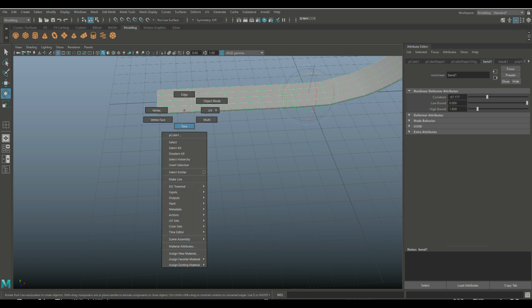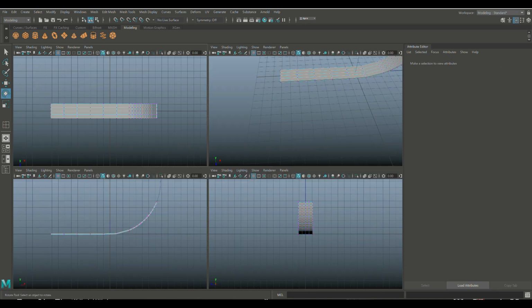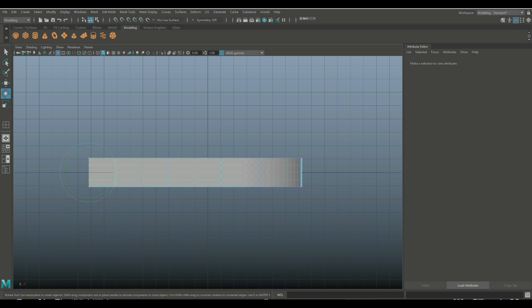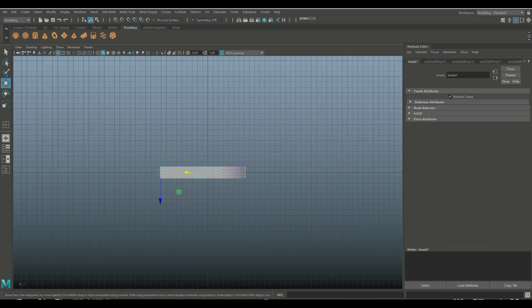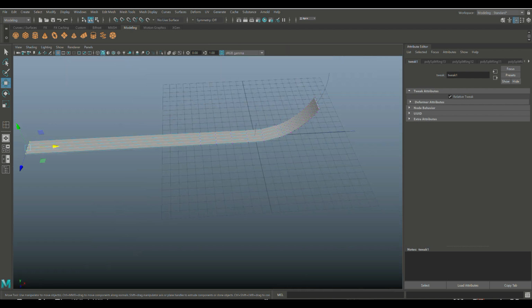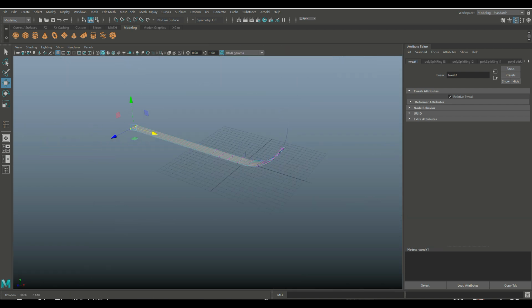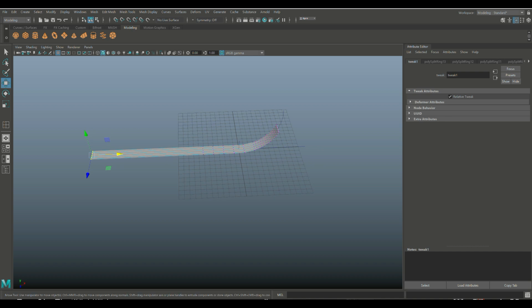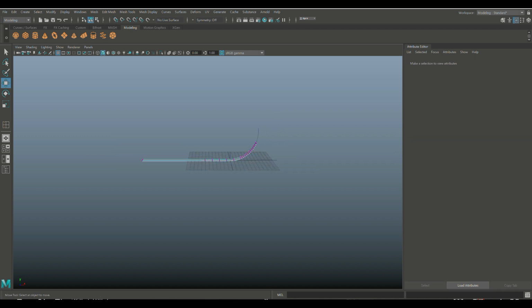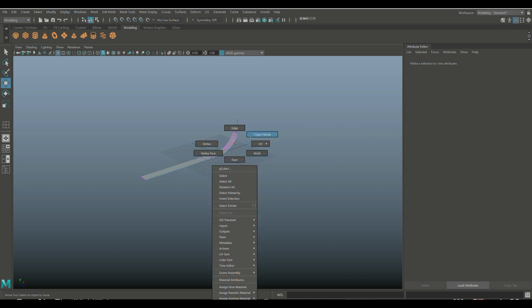We're going to right click and go to Vertex, jump to the top. Drag like this, hit W to move that, hold down X so we can snap it a couple of times until I'm happy with the overall proportions. And I don't need a lot of additional subdivision in that end over there, so I think that's okay. Let's see, maybe, yeah, maybe like that. So hold on X, snap it, there you go. All right, so we got that.